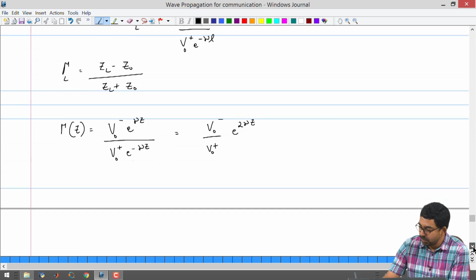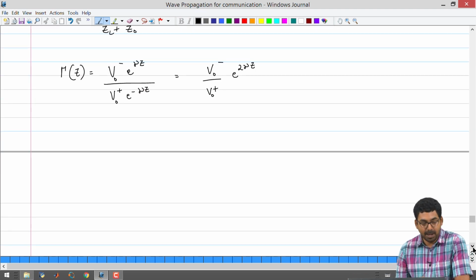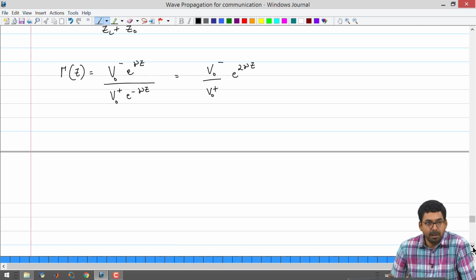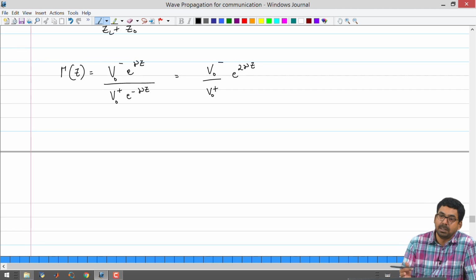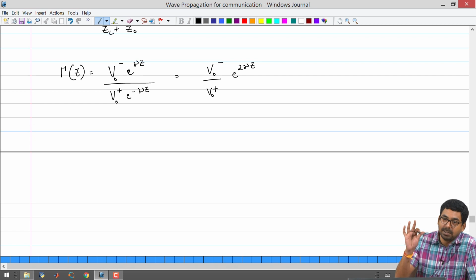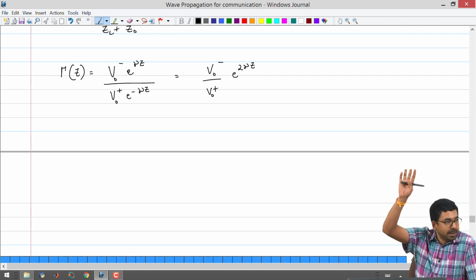Now, this reflection coefficient in the case of AC excitation also means that you will be having the superposition of the forward and a backward wave, and some instants of time you will be having the amplitude of the voltage going higher than the forward, alright, and the currents could be higher than the forward current, etc. Which means that we also saw from our simulations that there were some places where the voltage was pegged at 0 and some other places where it exhibited standing wave characteristics, like it was increasing with respect to time, but then going back.